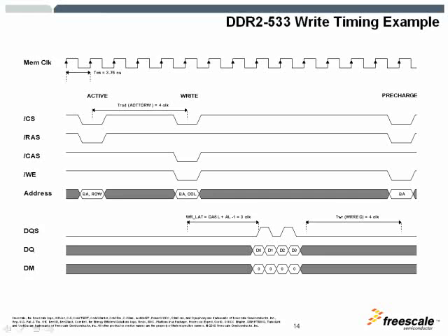Next, we're seeing another timing diagram here, and this is just the write timing diagram. As you can notice on the address and command bus, we see again the active command starting the operations. Active command opens the row buffer. Once the row is opened, the operation on the row can occur by a write command by providing the column address. Then a write latency later, that data will start to flow from the memory controller pins.